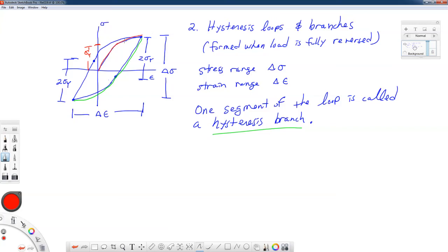But beyond that it starts to have some plastic strains, some changing of slope. Here we have an expanded range of 2 sigma yield before we yield in the cyclic case. And then we have kind of an expanded range of plastic behavior. This forms what we call the basis of Masing's hypothesis.